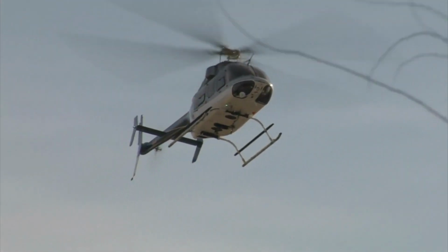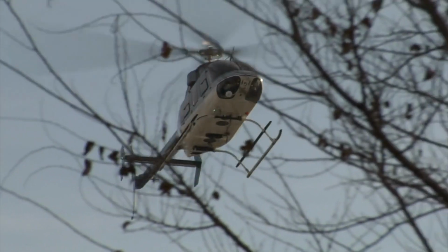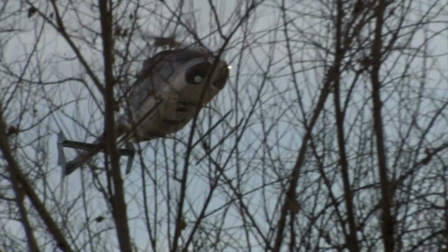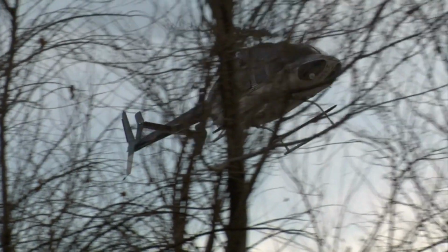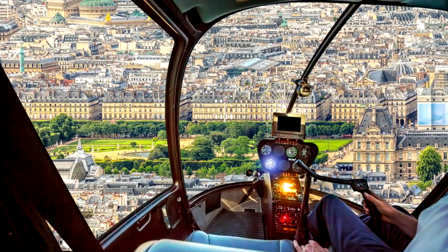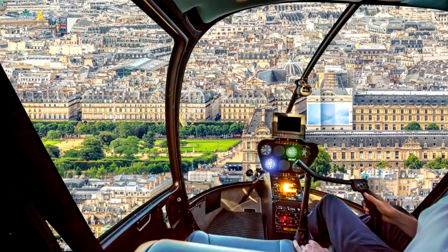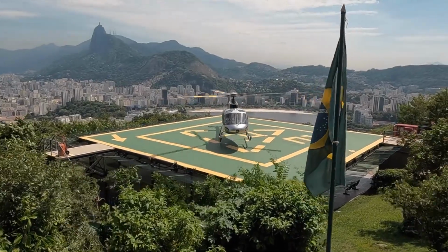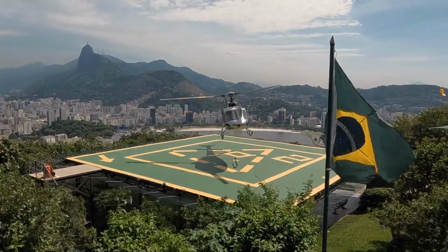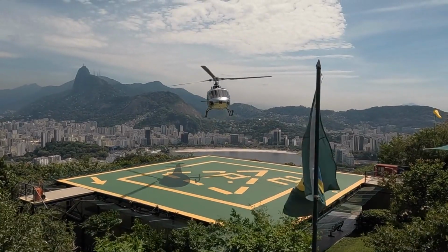Navigating the 180-degree portion demands anticipation of opposite pedal pressure due to the tail moving from an upwind to a downwind position. The tail's tendency to weathervane necessitates continuous pedal adjustments to maintain the same rate of turn. As the turn concludes, opposite pedal pressure stops the motion, and gradual forward cyclic pressure prevents drift.